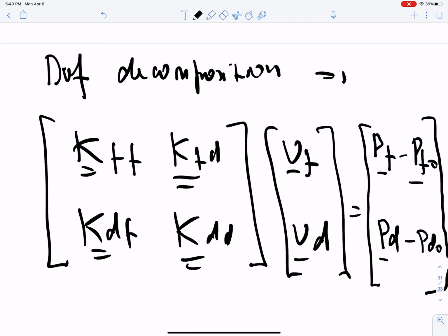Okay, you may ask, well, what is PD0? PD0, right, is going to be a contribution, right, of the applied forces, okay, like the distributed loads or temperatures, for example, right, to the degrees of freedom where the displacements are prescribed, okay. And so everything is done through IDs, it's automatic.